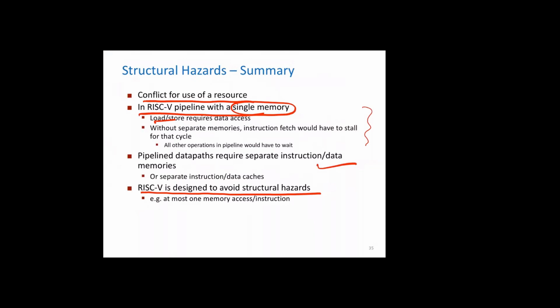A lot of these things we don't see because RISC is very simple, right? We have simply split the single cycle design into 5 phases that we have been studying right from the beginning, and so we have simply added buffers in between. Because of the buffers, the overall delay in a stage is limited, so the clock speed can be higher.